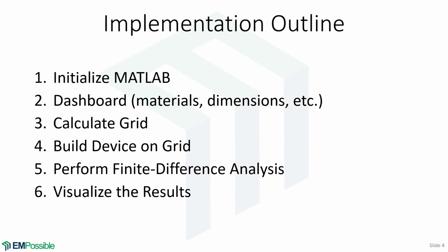We'll initialize MATLAB. At the very start of our code, we'll have something called a dashboard. This is where all of the hard-coded numbers go and anything to control our simulation. So we'll describe the materials, dimensions of the waveguide, and parameters about our grid that'll control resolution and size of that. And no work happens in the dashboard. After the dashboard, everything is done relative to the dashboard and no more hard-coded numbers.